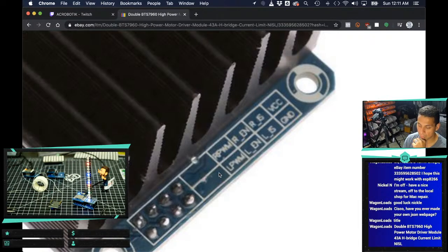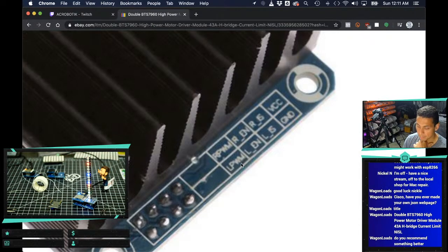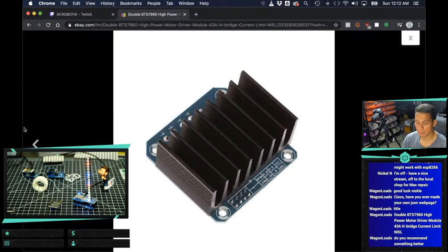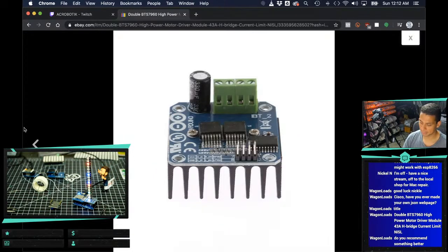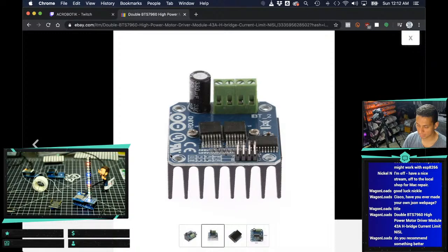I'll double check the spec on the H-bridge chip themselves, but I bet that VCC can be 3v3 or 5, or even if you put the 5 from the ESP on there, you can have the signals for PWM be 3.3. You can always use a logic shifter, a level shifter, but usually that works.